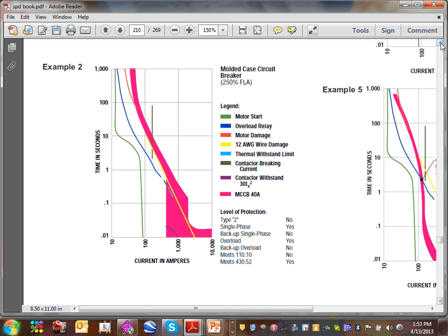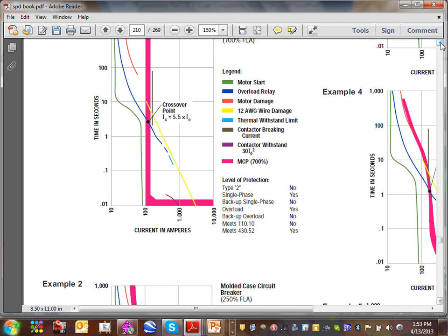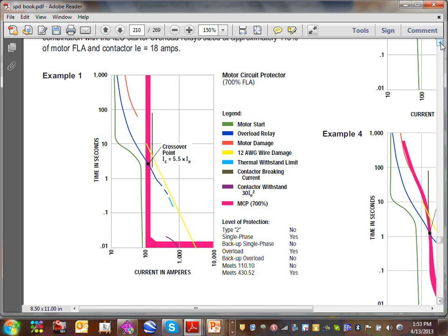Here's your circuit breaker. Here's another different type. This is an instantaneous trip circuit breaker. Did Jeff talk about this one yesterday, guys? That's where you size based on short circuit only, no overload, nothing. This is set at 700. We can set them up to what? 800.